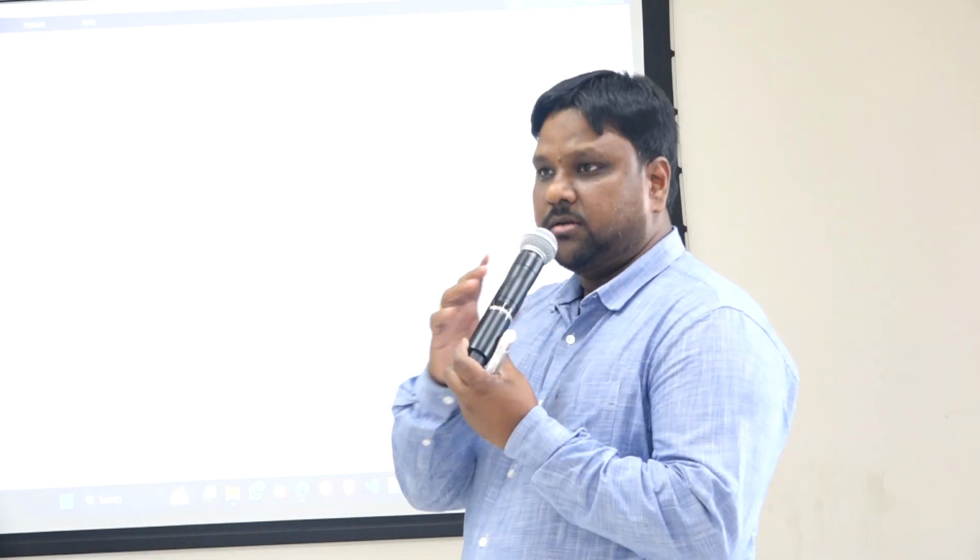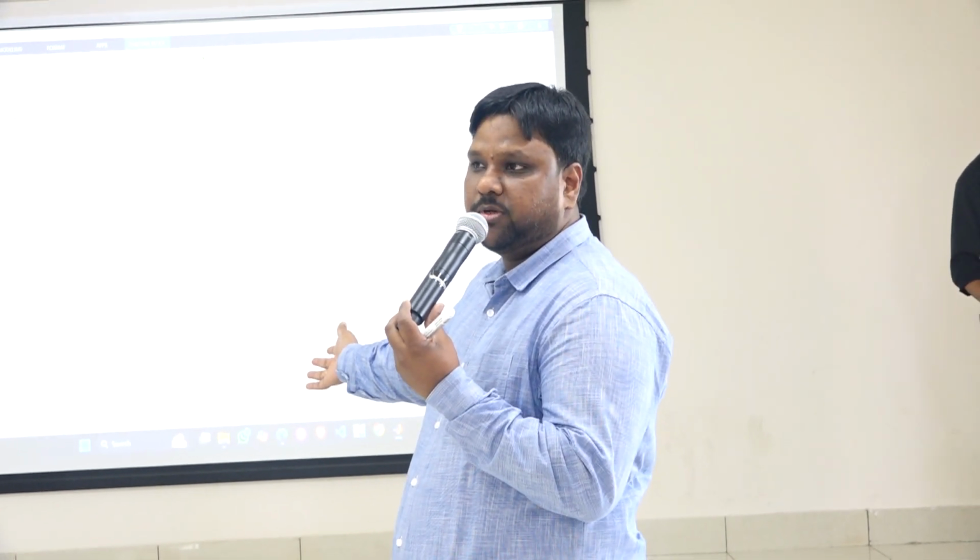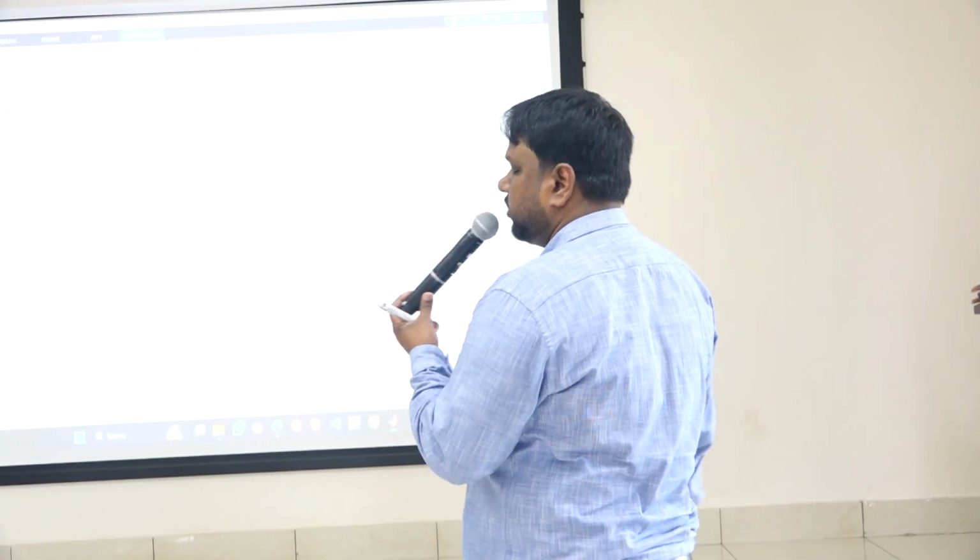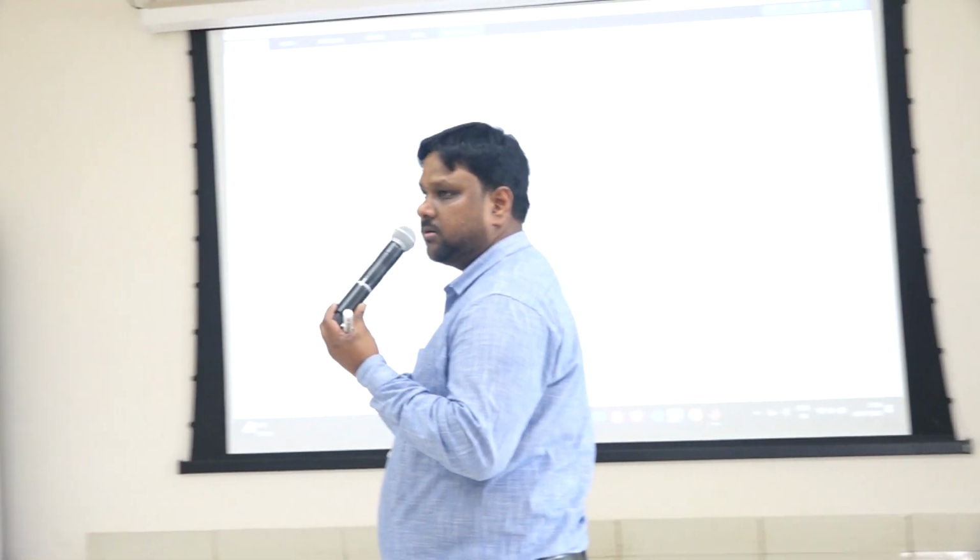This is the parameter which we are going to control using the principle of sliding mode control, okay? Right, I forgot to mention: the output capacitor across the secondary bridge, put its capacitance value as C naught, okay?